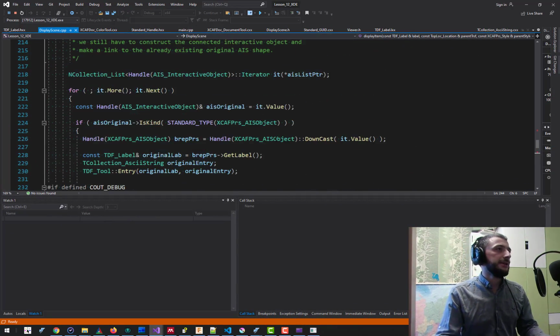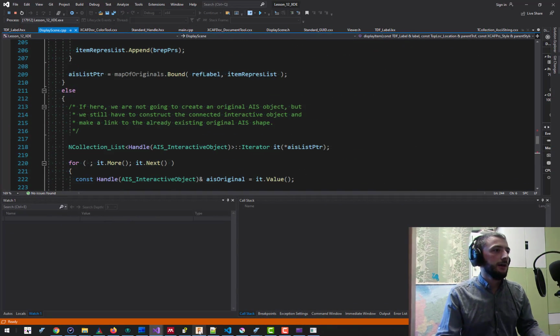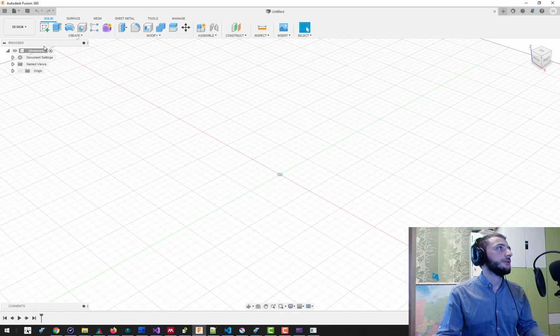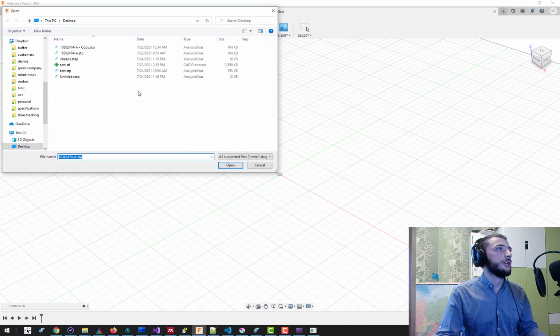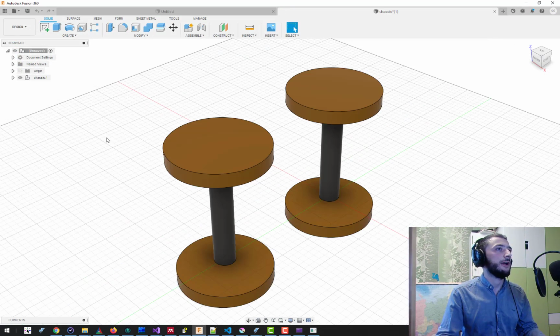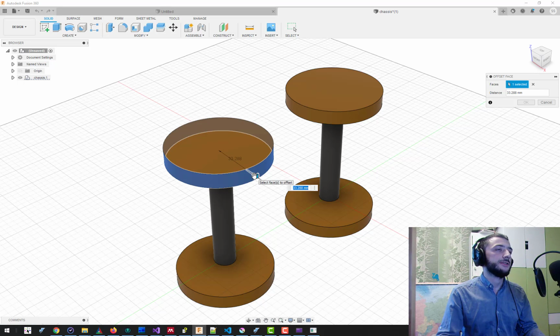So this is a pretty important thing which we discussed, and it has its own implications, like what will happen, because you see that I have only two prototypes in my hierarchical assembly graph for my solid object. So if I open this file, this chassis, then whatever I do with one of the instances of this object, if I modify this wheel here, all the instances of this exact object will also get the same modification.